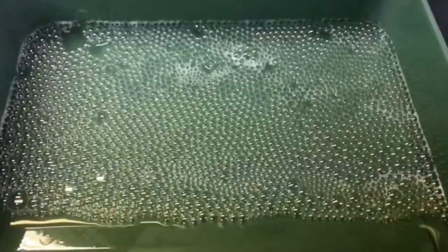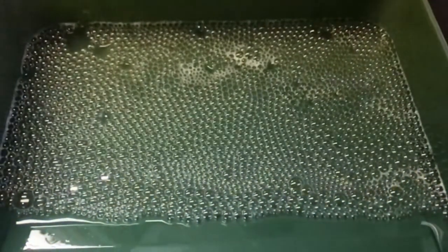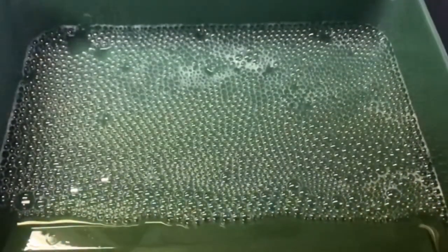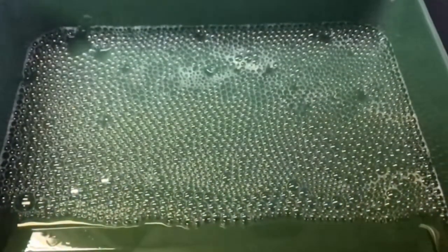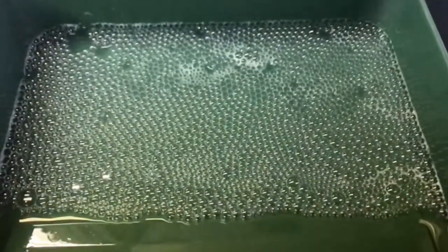This is shown on the bubble raft as different lines of the bubbles as they curve as you look at the raft. These boundaries usually result from the collection of dislocations along the grain boundary. The dislocations found in our bubble raft are all edge dislocations because it's a 2D plane. These edge dislocations are caused by interstitials and vacancies in the bubble raft.